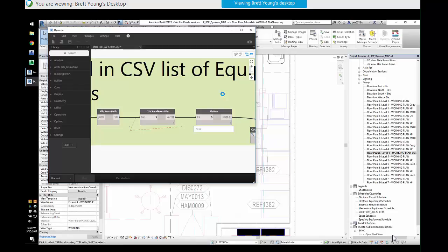Rather than going through a CSV file, would it be easier if the architect put in a yes or no applying parameter? Yeah. Yes. I would love that, not only that, but that the equipment has amps or horsepower or kVA included in the family, so I don't have to look at a table as well to figure out what the load is, right? I can read the load in from the same thing that I'm doing right now and work on putting that load into my disconnect family or my junction box family or whatever.